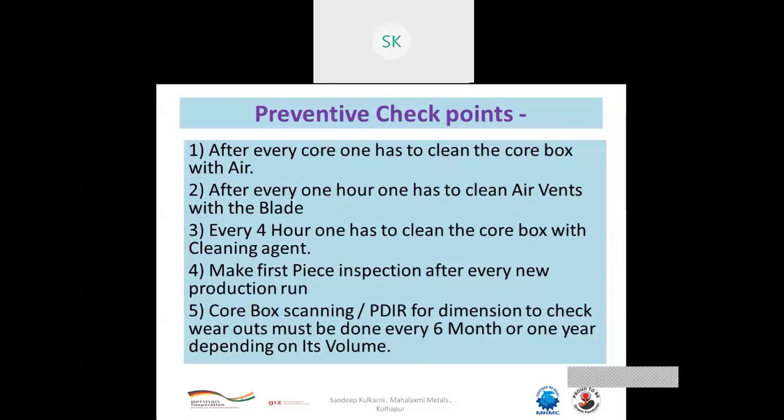Every 4 hours, one has to clean the core box with a cleaning agent. This is also important, that every 4 hours you clean it with the cleaning agent, so that whatever deposition is there on the core box will get released.